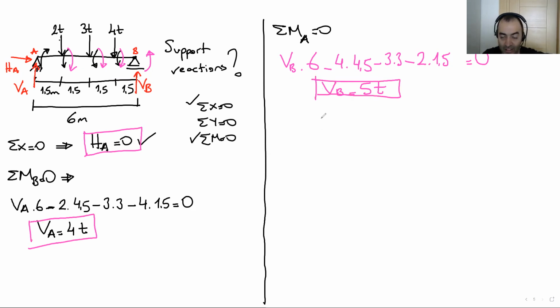Okay, what I suggest is to check your calculation, because you're using a calculator, you can push a wrong button and get a wrong solution. That's why I always suggest doing a check. Myself, in my calculations, I do it. I check myself. I use total Y equals 0.